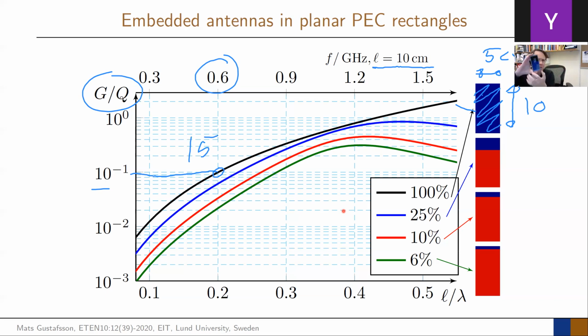That's good. But on that side, you have to put a screen, which means you're not allowed to do this case here because you're not designing an antenna. You're actually only designing an antenna that has to live in a small size next to the screen or on the sides that sits here. So if we change the perspective here, and we take instead this green curve that sits there, then you design your antenna up there. So that's what you do with your antenna. And this part down here is now PEC, which is approximately the screen that sits here. It's a good conductor. In this case, it's also infinitely thin.